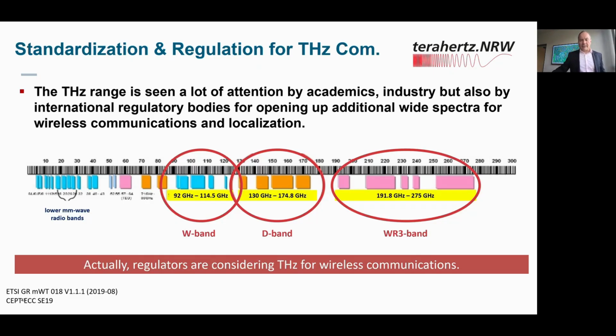And if we want to answer this question from the technological point of view, there is a lot of work still to do in the integration. Not only the photonic integration, I've showed you some examples of photonic integrated circuits, like this integrated chip for beamforming. But if we want to have everything integrated in photonics, we need different semiconductor structures. A laser is usually made of indium phosphide, and this very low loss beam steering chip is made from silicon nitride or sometimes lithium niobate on silicon photonics.